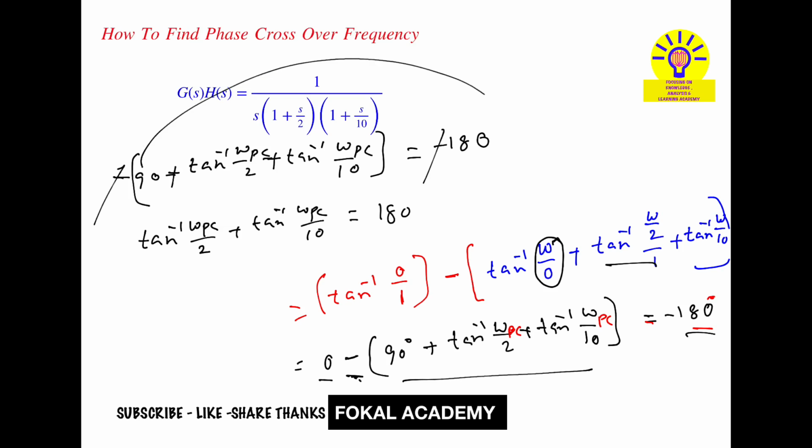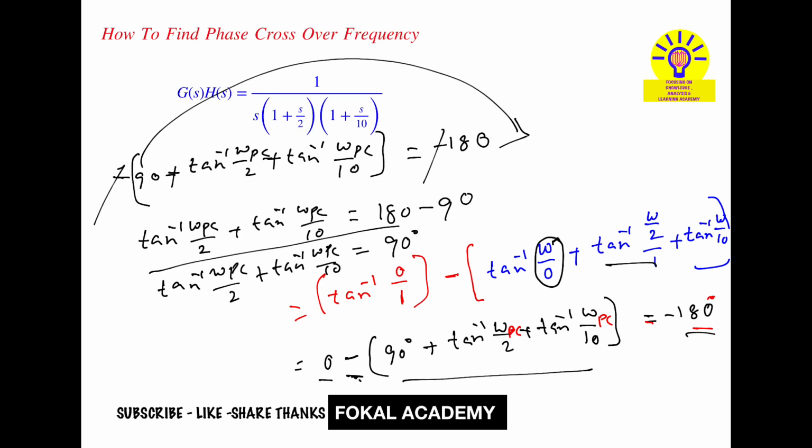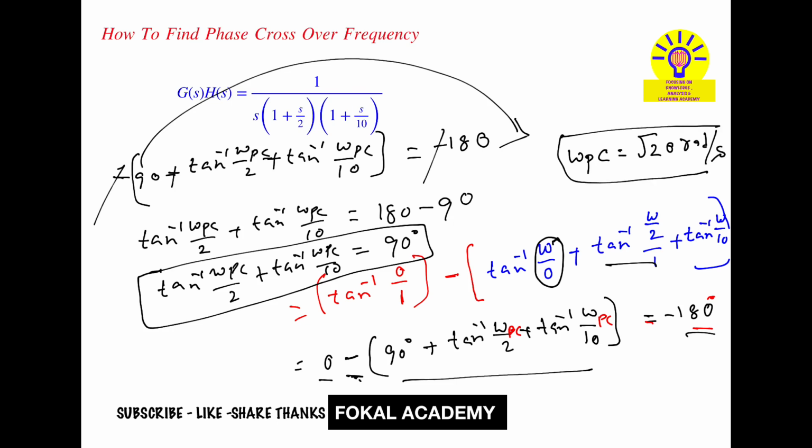Bring this 90 to the right hand side, it becomes minus 90, so the right side becomes 90 degrees. It is tan inverse of omega pc by 2 plus tan inverse of omega pc by 10 equal to 90 degrees. Now by using a calculator, we will get the omega pc value. By simplifying that, we will get root 20 radians per second. This is the phase crossover frequency. At this frequency, the phase angle of the open loop transfer function is minus 180 degrees. This is the required frequency for the given problem.